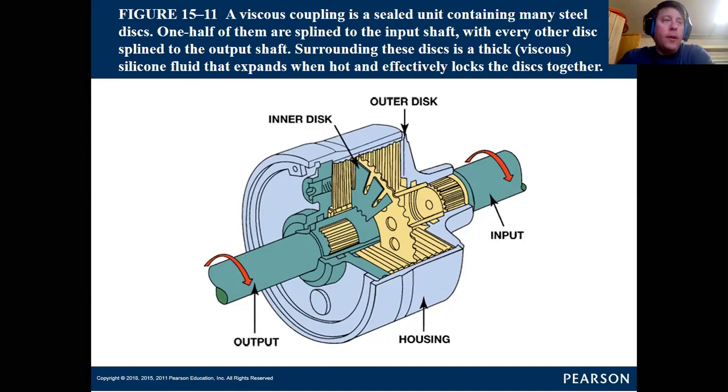Believe it or not, most of these all-wheel drive vehicles are not truly four-wheel drive. They're a power split of maybe 70% to the front and 30% to the rear, meaning that they can't actually transfer 50% of the engine's torque to each axle.